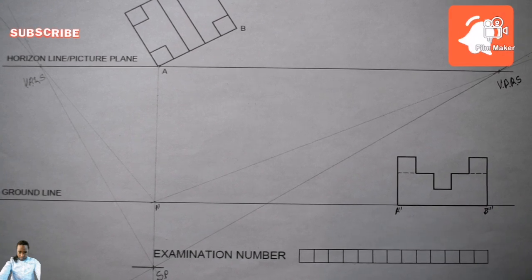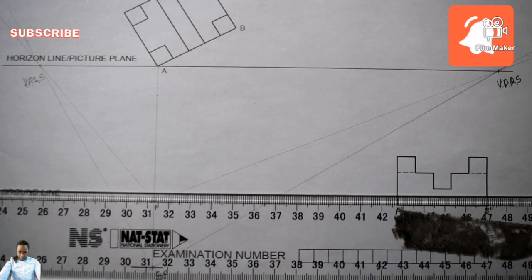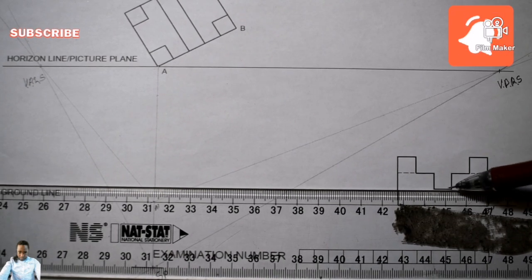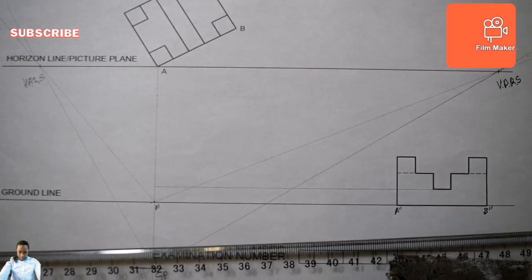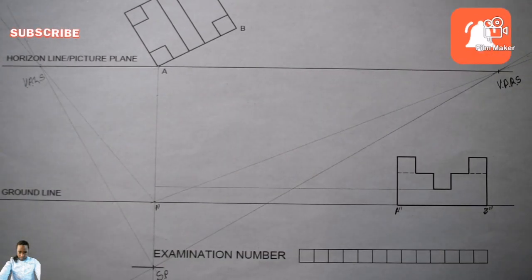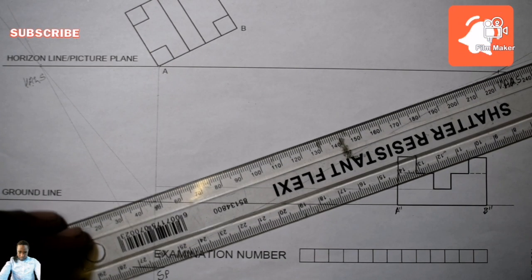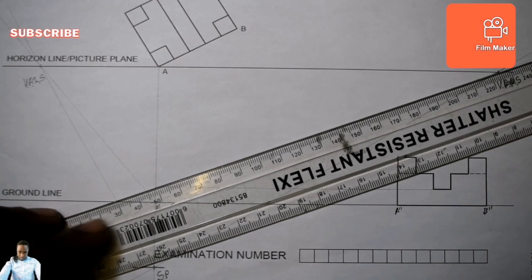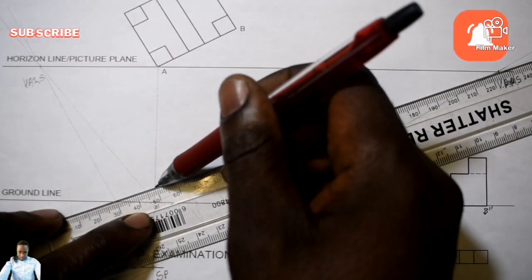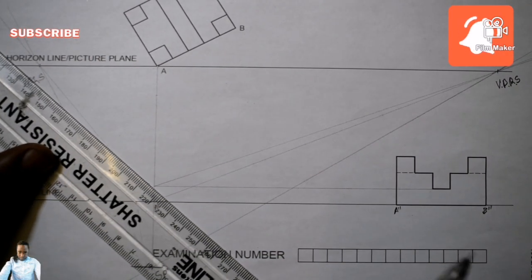You understand? So now I am going to take all the points that are behaving vertical from our right view. Take this one, and once it touches this vertical line, I'll stop. I'll take it to my vanishing point of my right hand side. There you go, and I take it to my vanishing point of my left hand side.